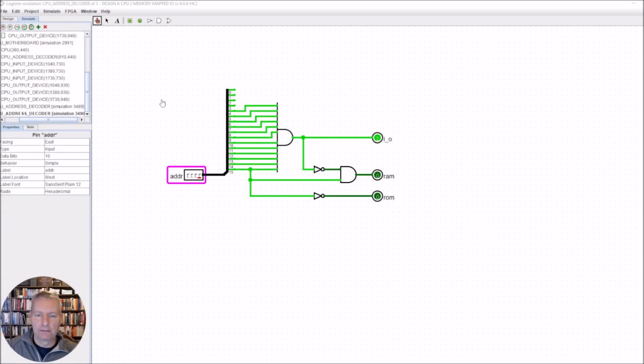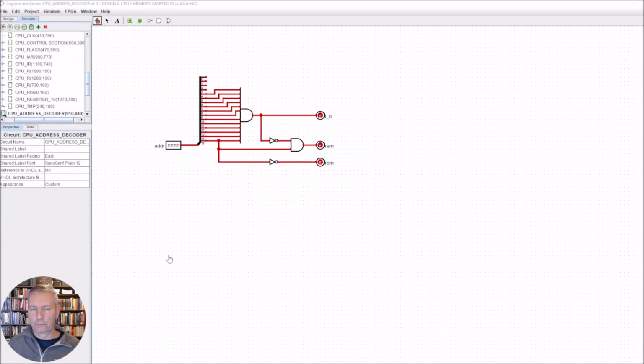So I've taken this and generated an instance of it. An instance simply has the address coming in from the memory address register, and it splits it into these 3 options: an input/output, a RAM and a ROM. Now this is where things are going to change a bit. I'm going to go to the next level up, but you'll notice that there have been some changes made, so don't worry when we look at it and you don't recognise it. We will talk our way through it, and it will also be available to you in the resources section.